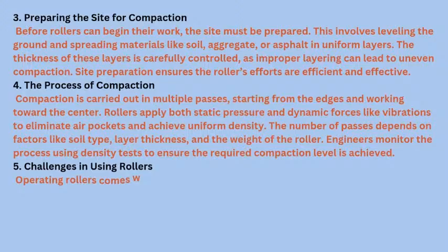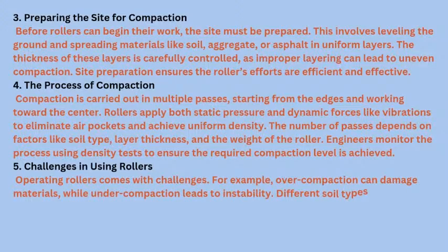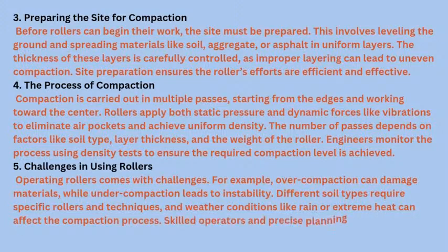5. Challenges in using rollers. Operating rollers comes with challenges. For example, overcompaction can damage materials, while undercompaction leads to instability. Different soil types require specific rollers and techniques, and weather conditions like rain or extreme heat can affect the compaction process. Skilled operators and precise planning are essential to overcome these challenges.